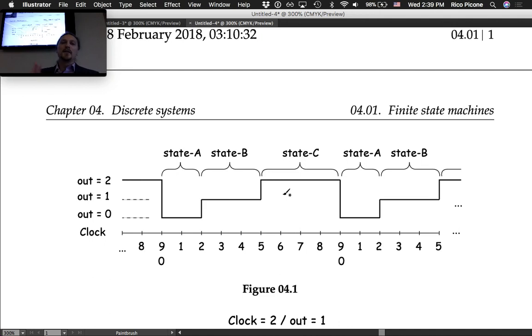The other times, at each clock count in between, these intermediate ones, we don't do anything. We just wait. We wait until this condition happens. And so when you're in each state, there is a set of conditions with your state and your inputs that you're monitoring. And you're waiting for that transition to occur. And then when you're ready for that transition, you make it.